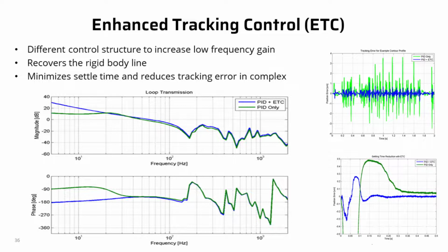And the blue line, when I put this new friction compensation in place, is matching the inertia line, as I would expect. And the result, if you look on the right side here, you can see a blue curve, which is with the friction compensation on, and the green curve without it on, and again, just drastically decreasing that settle time as you come in to the system.